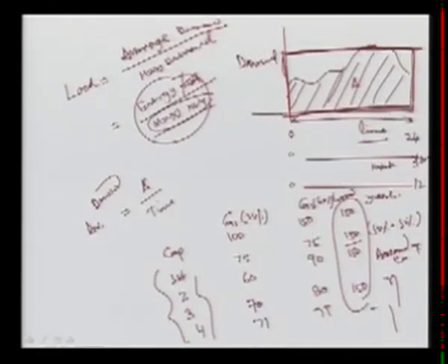Here we always try to go for economic dispatch, which means we have to run the system so that we can achieve the minimum cost. The cheaper generators will generate at 100% loading, and the expensive ones will be reduced. For example, let's suppose G1 is very cheap, so it will go for 100 megawatt and the remaining 50 will come from the expensive generator, so that we can achieve the minimum cost generation. That is the major criterion for this.